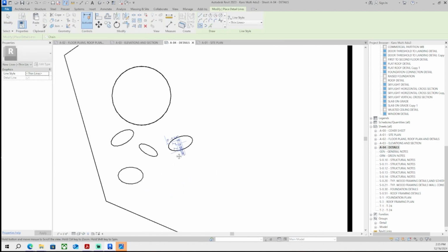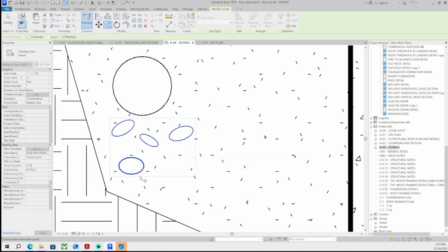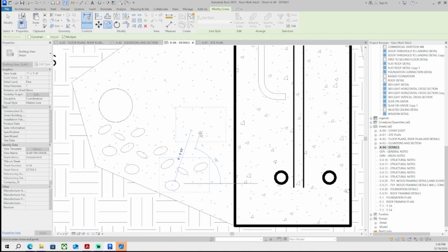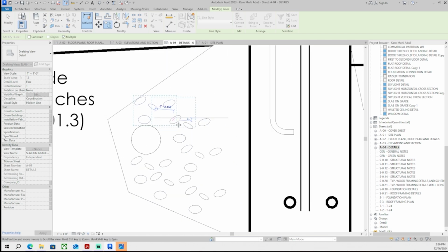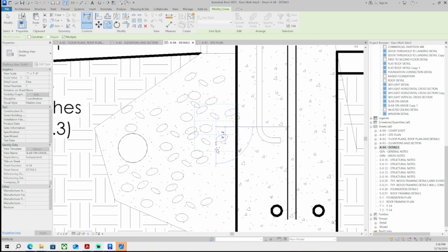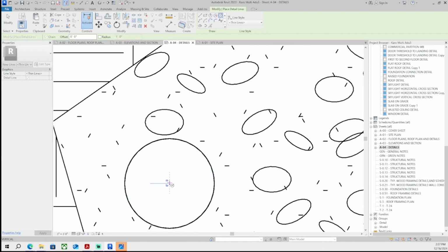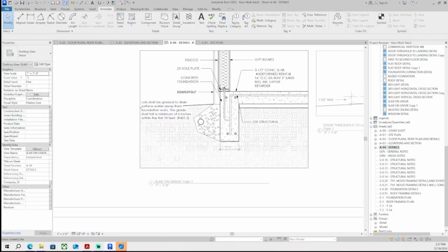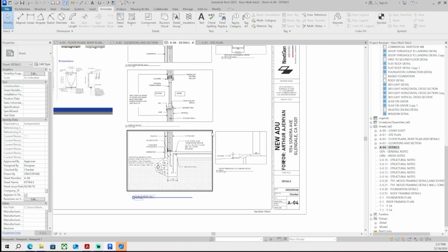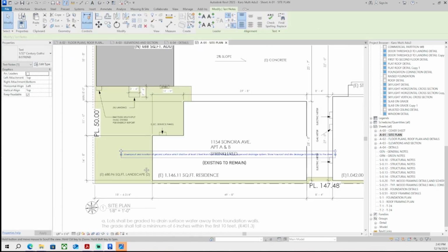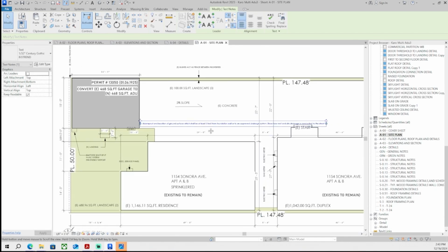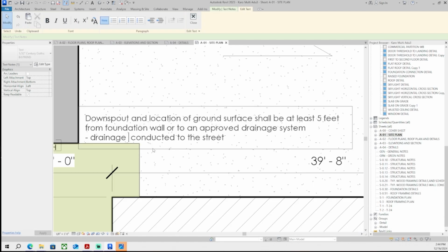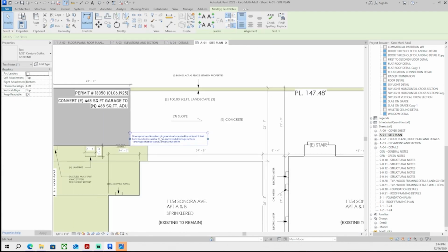Sometimes you'll have to pull it through underground and drain it out into the street or into landscaping. Then you'll have that pipe there taking it, sloping it away, and you have the French drain with rocks here. I couldn't find that hatch. Revit by default didn't have it, and we didn't have the family. So I just approximated it by putting the concrete hatch, which gives you the dots, and then putting in the rocks, and then offsetting the drainage pipe to give it the thickness.